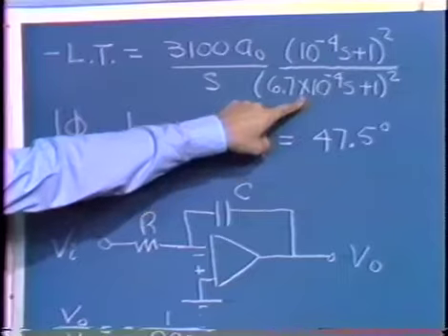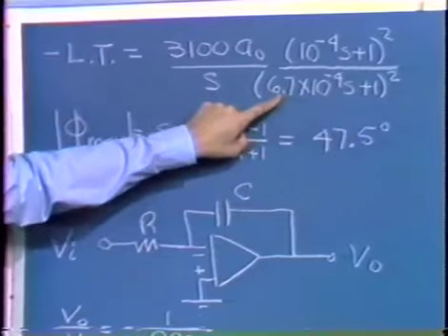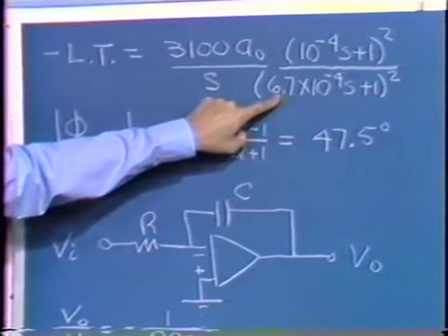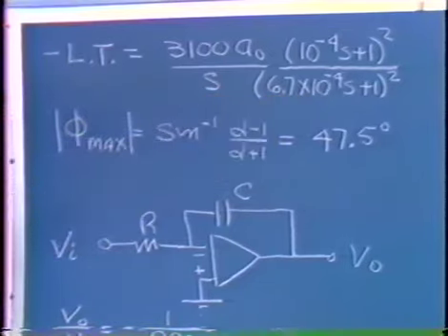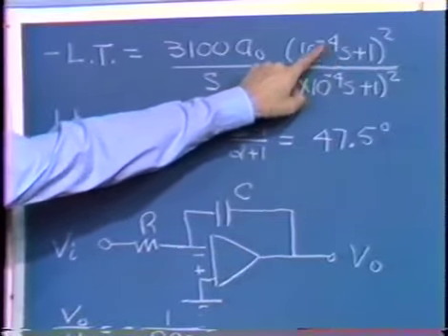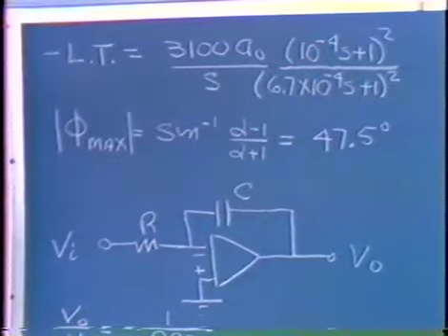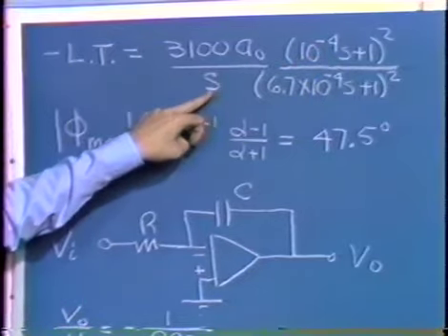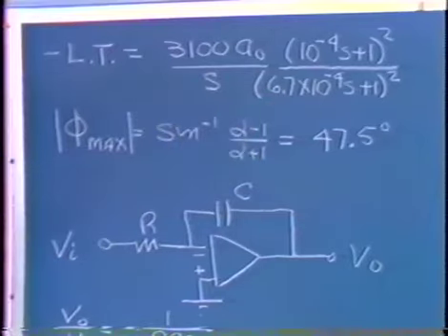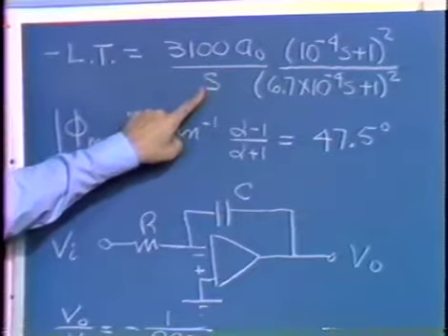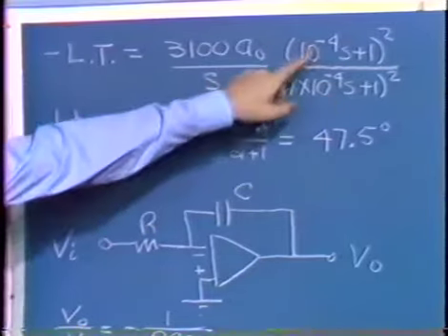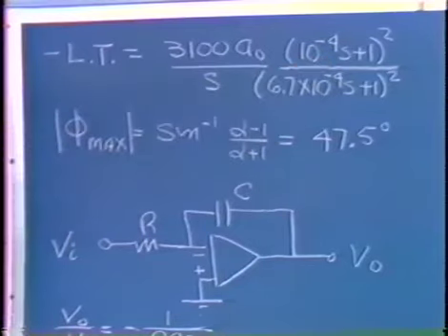We have two poles, two coincident poles, located at 1.5 times 10 to the third radians per second, the reciprocal of this time constant. And then we have two higher frequency zeros at 10 to the fourth radians per second. This differs just a little bit from the description I gave earlier, where I assumed three coincident poles, but that's not a fundamental difference. Here we have one pole at the origin, two poles that are coincident further out, and as I say, then the two zeros.